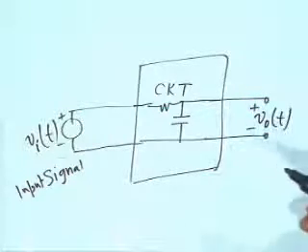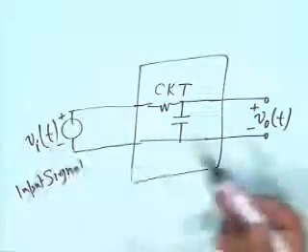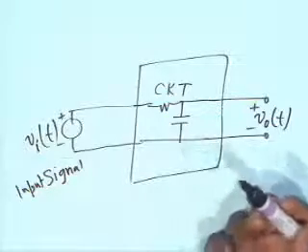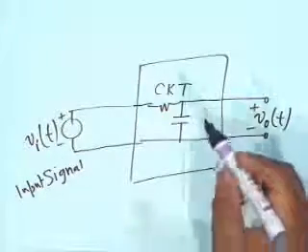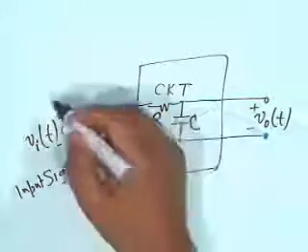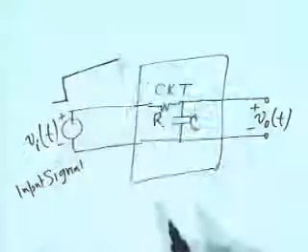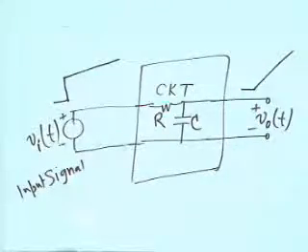The functional form is different, that's why V0 is different from VI, and this is a very simple example of a signal and system interaction to produce something useful. For example, you know that this RC circuit is an integrator, and therefore if you put here a waveform like this, if your VI(t) is like this, then what it shall produce is a linearly going ramp. All right. So this is an example of a system and its interaction with signals to produce something useful.